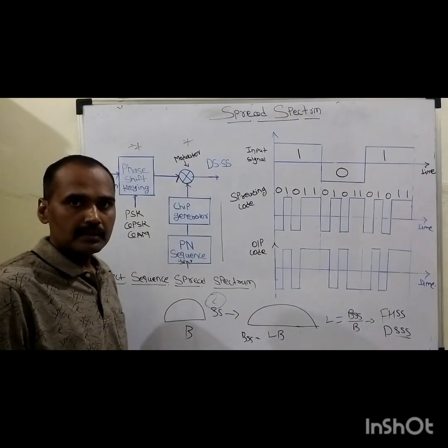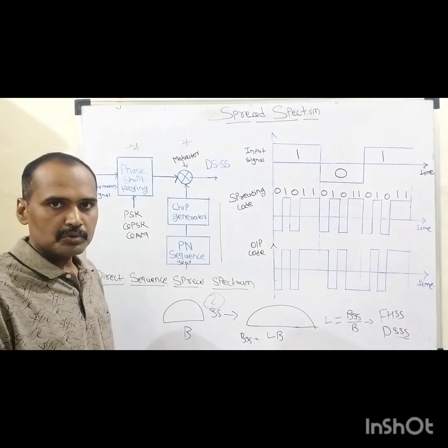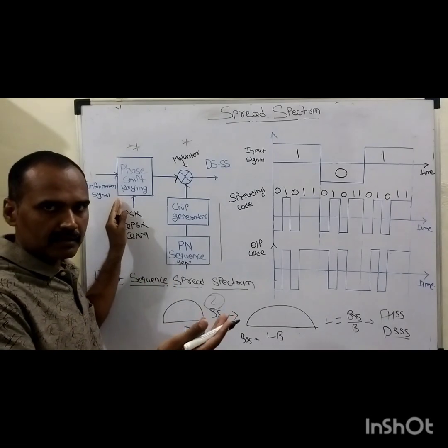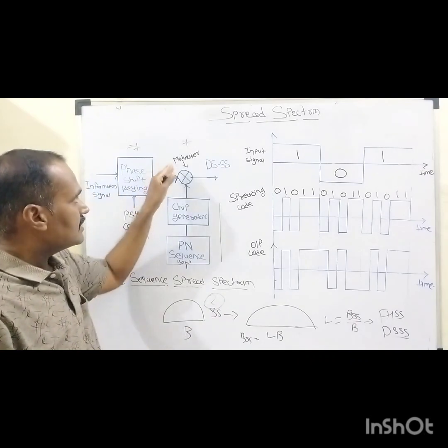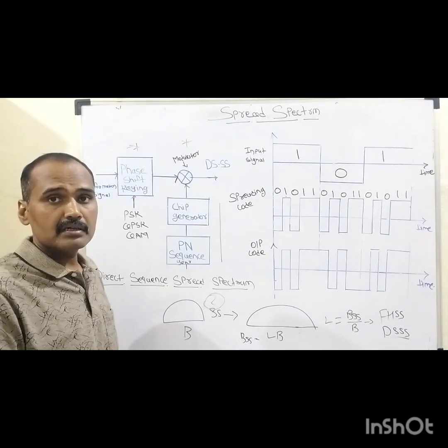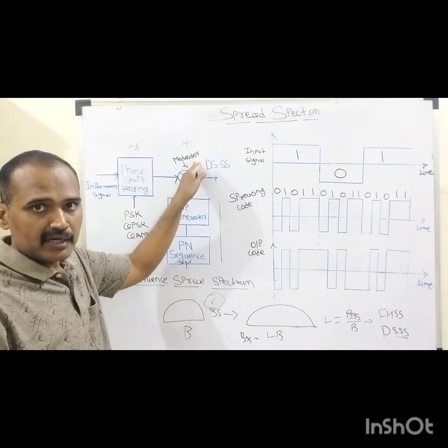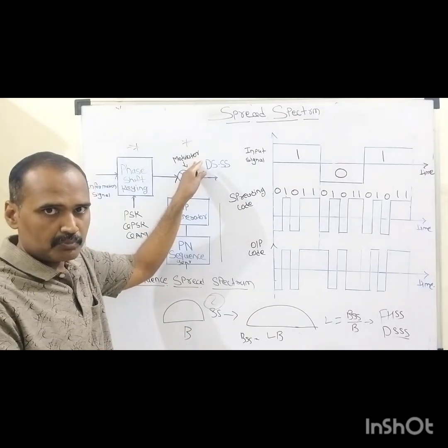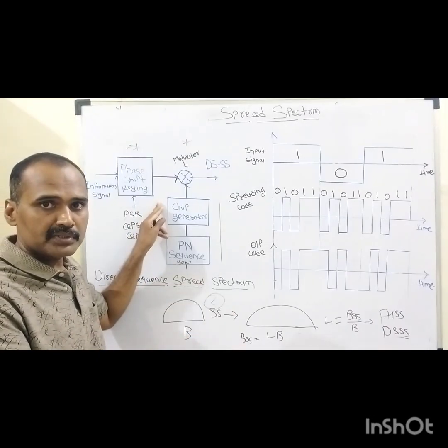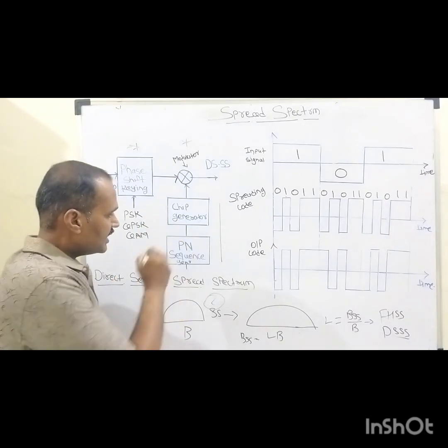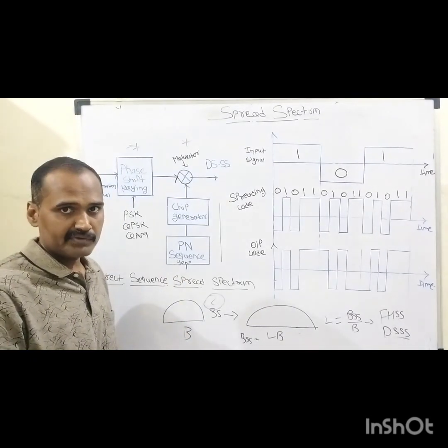So after going through the first level of modulation, the desired symbols or signals emitted by either the single carrier continuous wave digital modulator or the multi-carrier continuous wave digital modulator are given to one input of the second modulator, the spreader, which we can also call a type of amplifier. This desired symbol sequence is combined with the lower terminal of this modulator, which consists of the chip generator operated by the PN sequence generator, or the spreading sequence generator, right?